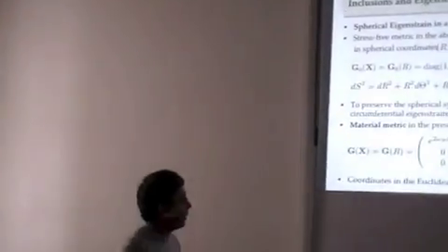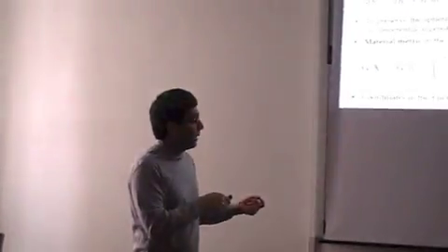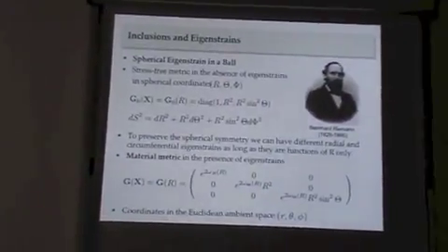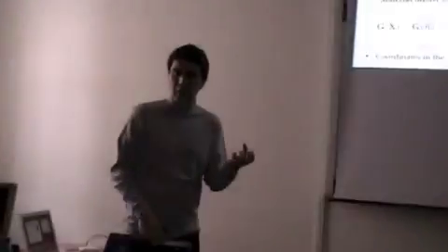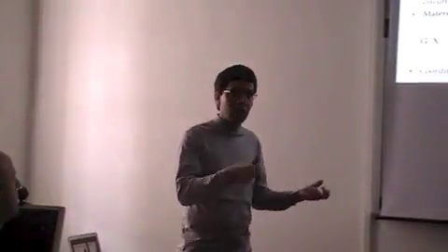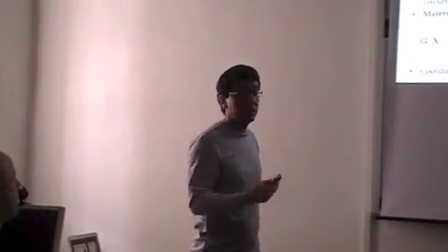I would have radial and circumferential eigenstrains that are not necessarily equal. And then at the end, if I have pure dilatation of eigenstrains, they're equal. But I'm able to solve the problem even when they're not equal.